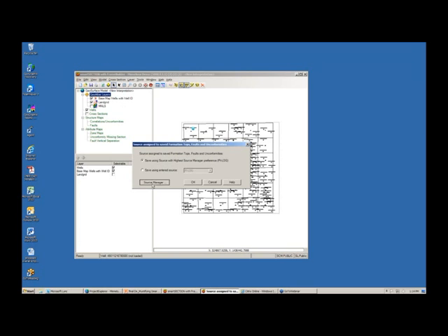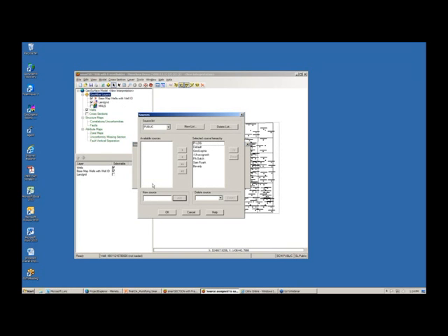This is extremely important because it's here that you establish the integrity of your data that you're going to be using. So you're probably all familiar with Source Manager. It is the manager that controls what sources are used in Wellbase, and now the same will be true for smartSECTION. We put all our sources on the selected source hierarchy side, and as you know, the source that's at the top is going to be the source that's going to be displayed and used first. If the first source does not have a pick associated with it, it goes to the second, third, and so on. I highly recommend using your own personal user-defined source list and eliminating all sources that you don't like or you don't think are very good because they can ruin a model. So it's very important to choose your sources wisely.